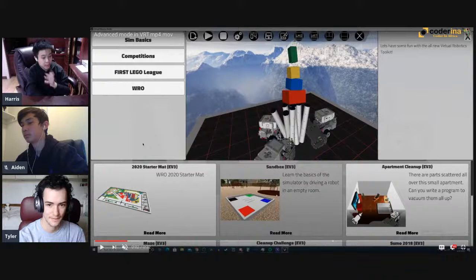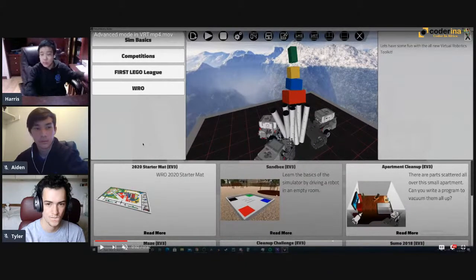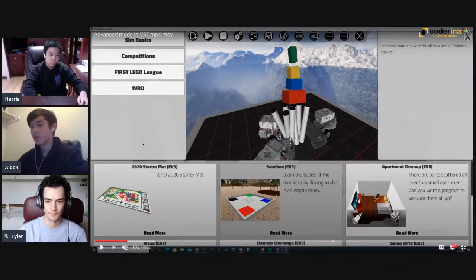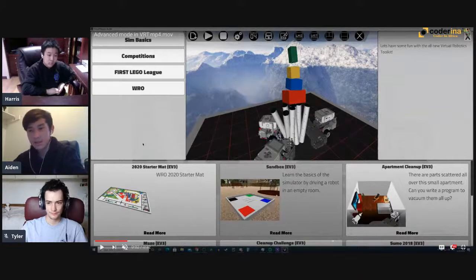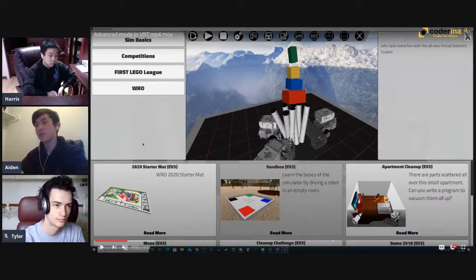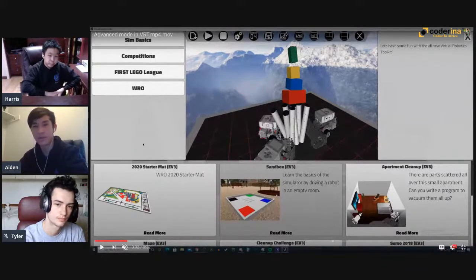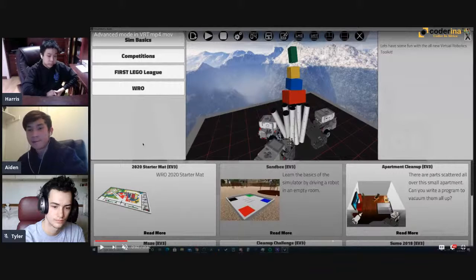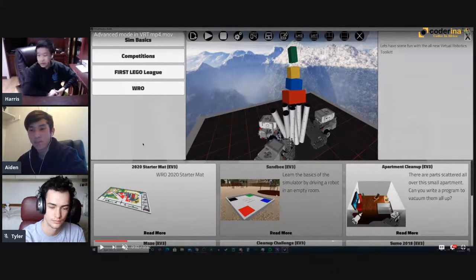Aiden, do you have any mention on it? Because Aiden has been to World Festival for FLL, about how long batteries last. Oh, yeah. For the batteries, they would usually last throughout the whole tournament. But the thing is, if you're using the rotations for movement, then when the battery gets below half, the robot will slow down a significant amount. So if you're doing competitive stuff, I would recommend you bring 3 batteries just in case.